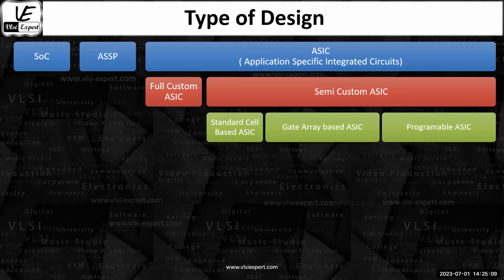So there are going to be different specifications. You are going to design it in advance, and then the designer is going to use them as it is. They are not going to customize it. They will just use it. So if in your library there are 10 different types of inverter, then you don't have any option to use an 11th kind of inverter. You have to design your chip based on those 10 different inverters only. So that's basically the standard cell based ASIC.